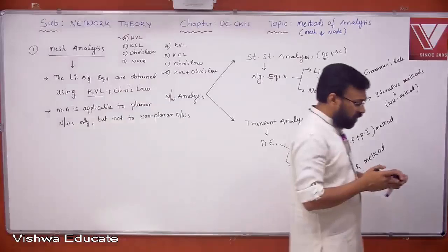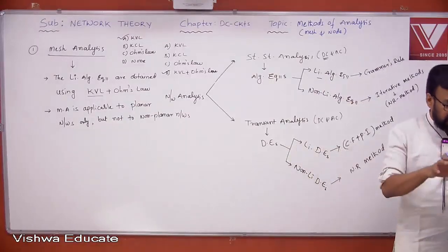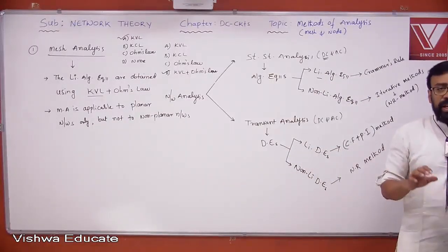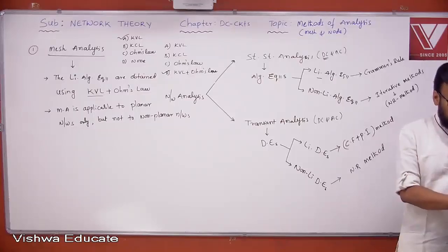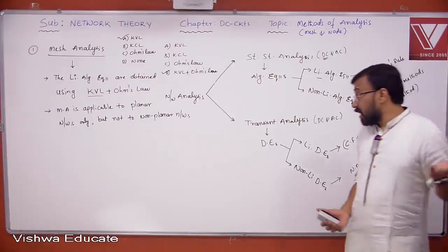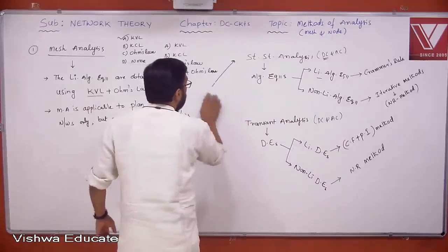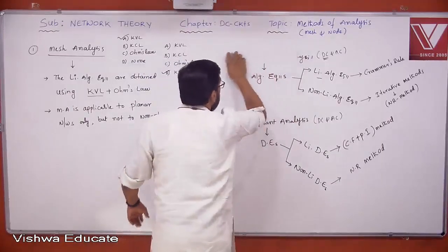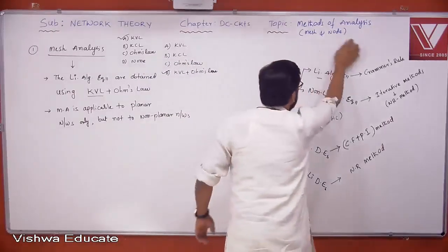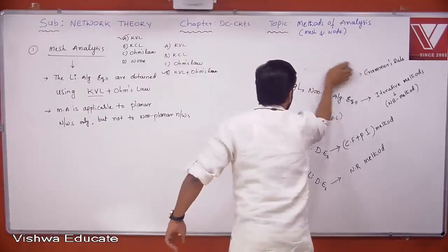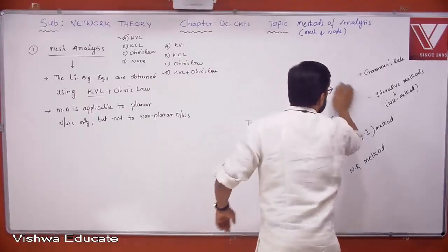What is the disadvantage of mesh analysis? If somebody is asking a question, you must tell that it is applicable to only planar networks, but not to non-planar networks. But you must also understand what is planar and what is non-planar. So write down planar network. Put the heading planar network. Write down.